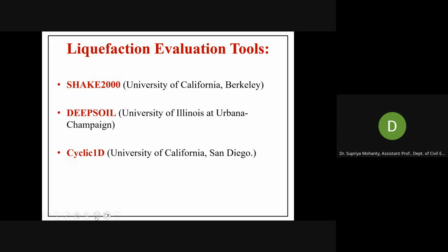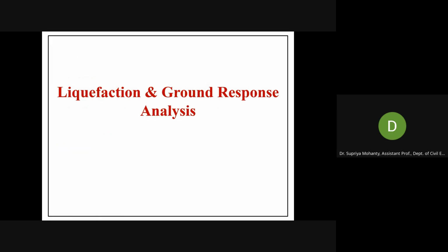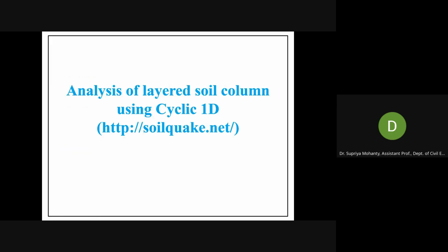There are many liquefaction evaluation tools available, open source, free to use. Cyclic 2000, developed by the University of California, Berkeley, you can use for your ground response analysis. DEEPSOIL is another open source tool; a student version is also available, developed by the University of Illinois. And Cyclic 1D is another open source tool for ground response analysis, developed by the University of California, San Diego. So these are the tools that can be used for liquefaction potential evaluation, like liquefaction ground response analysis.